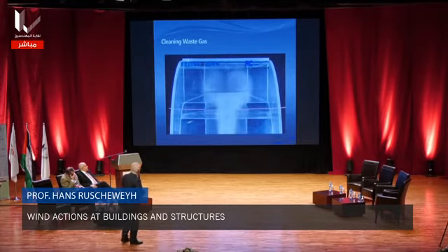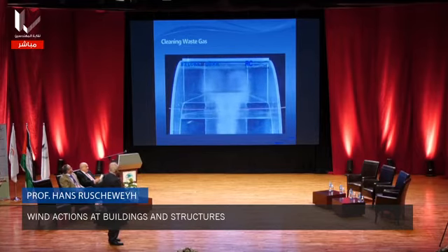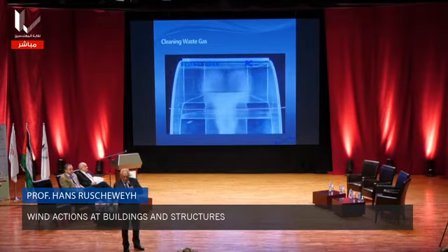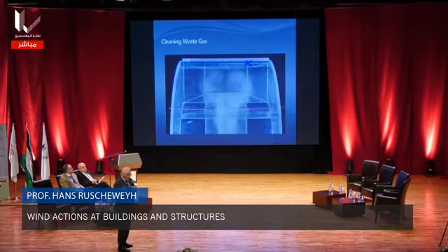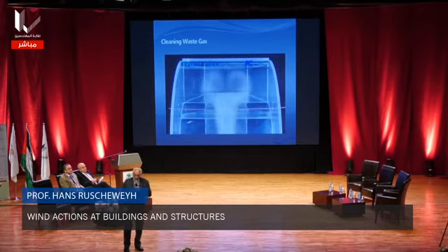So to clean it, in the power plants, we have installed such a system, and it is based on a vortex system. It's a so-called leading-edge vortex system. This is here a model test, and the ammonia must be injected into the waste gas. Ammonia and the NOx is cracked in the catalyst. It is installed in the cars, you know it. And we use it in power plants, and we have received removal rates of up to 97%. And the diesel cars, which are on the market, have a removal rate of 60% or 70%. So my proposal for the companies is to use our mixing system in order to increase the removal rate, and I hope they will do it in the future.